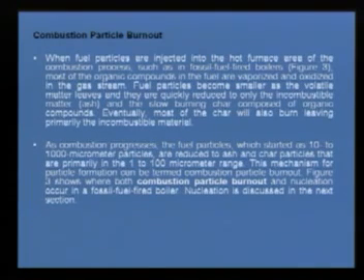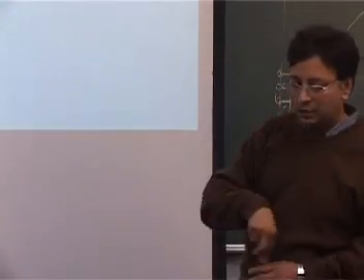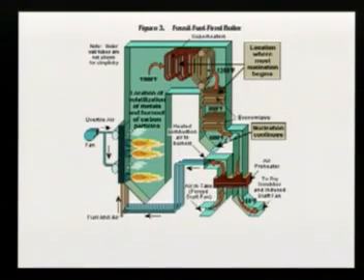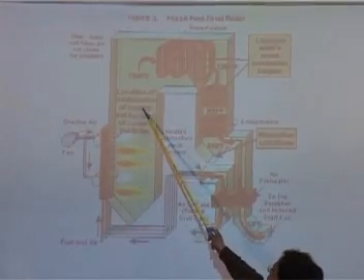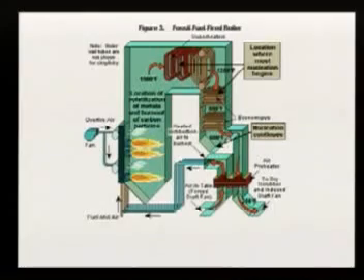When the combustion particles burn out and nucleation occurs in a fossil fuel fired boiler, nucleation is discussed a little later in this section. So we're just talking about the particle burnout and everything together here. Once you are firing the particles, this is the air which you are firing. The particles may be much larger here. The volatile organic matter and some of the metals, for example mercury, will quickly evaporate, where some metals won't, but mercury, in fact lead also to a large extent, will evaporate. Then the cooling is there, and then separating the location where the most nucleation occurs.